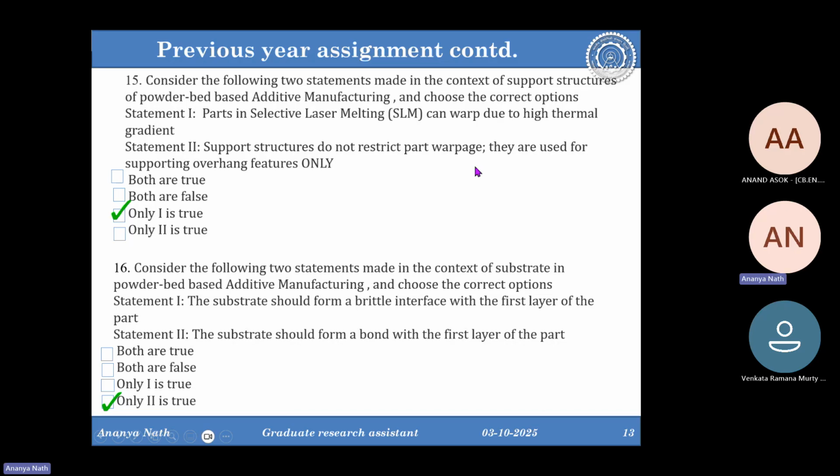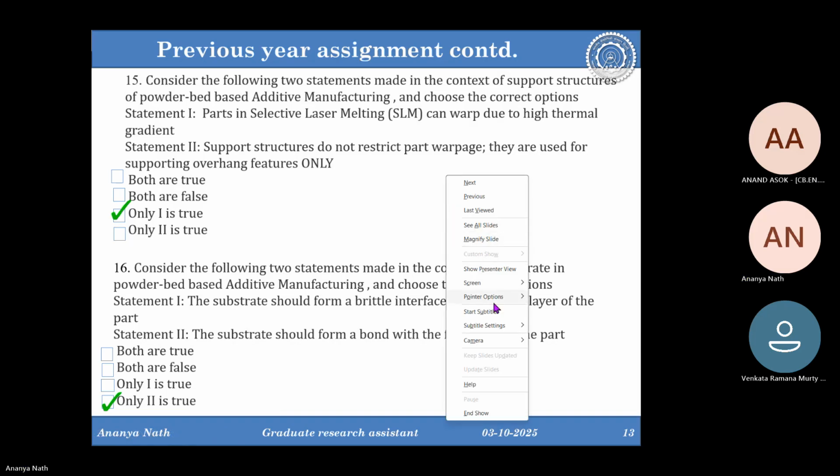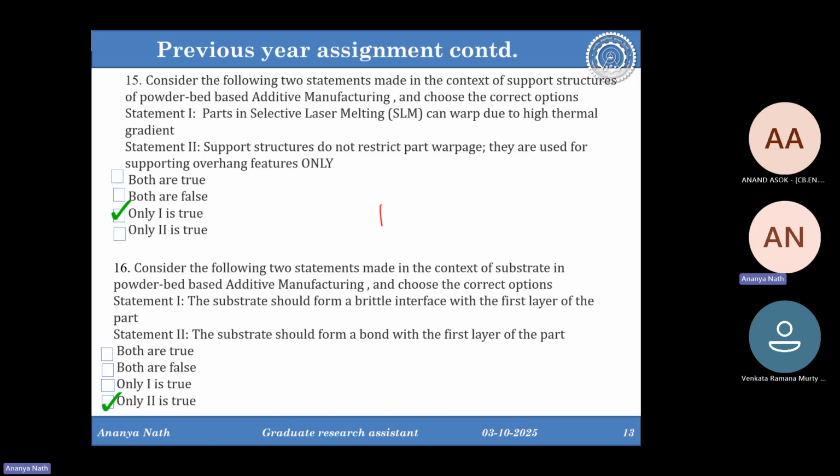When you cut the part, how can we cut that? Can you explain? If you have the substrate here and the part here, we cut the part from here. We don't sacrifice the substrate. We sacrifice a few portions of the part. After cutting from the substrate, the part will look like this. Then if you grind the substrate, only a few microns of the substrate are gone.